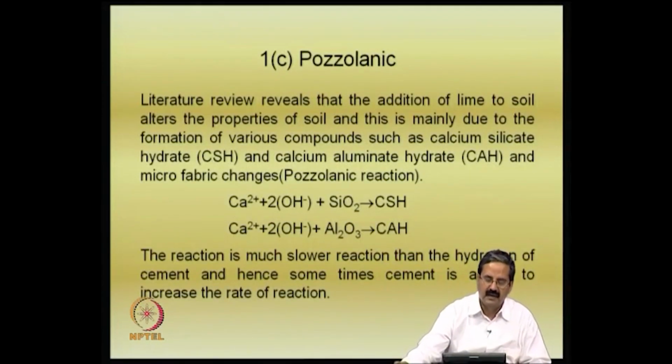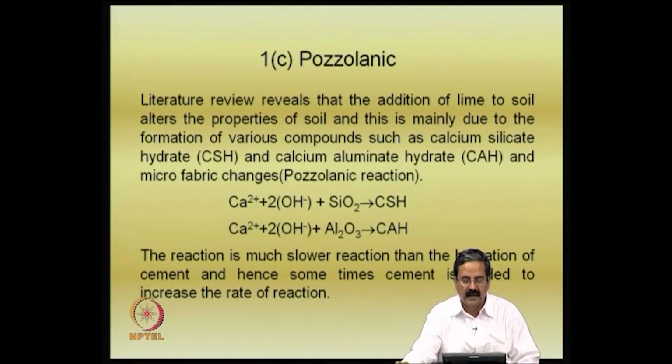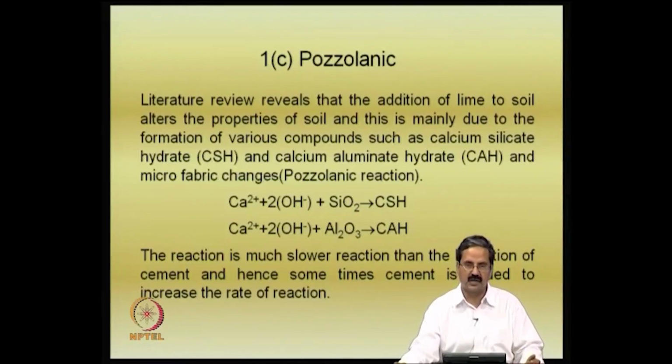Another important property that we should understand is that lime gives a pozzolanic character to the mixed soil. What it means is that it results in calcium silicate and calcium aluminate hydrate materials, and also changes in the fabric. We understand that the same compounds also exist in cement. It is like a cementitious material trying to behave.